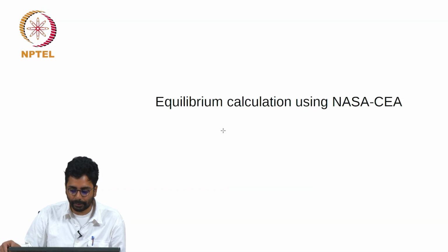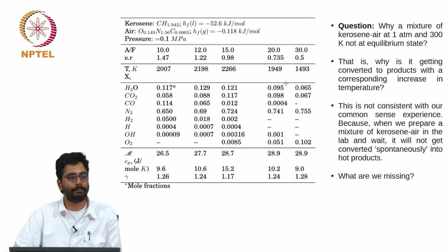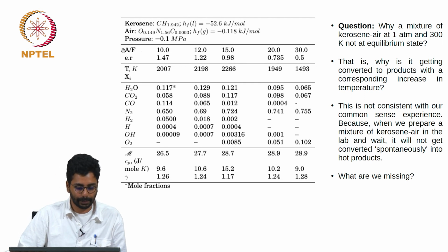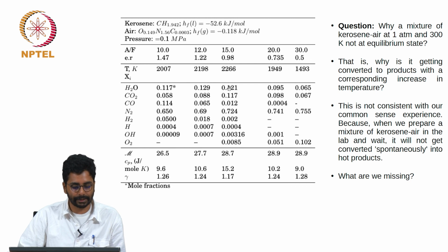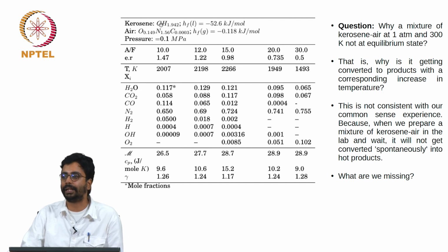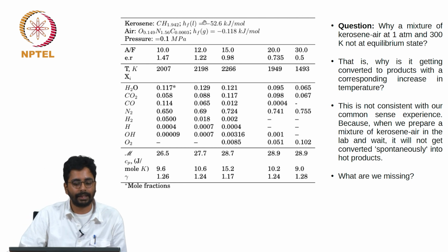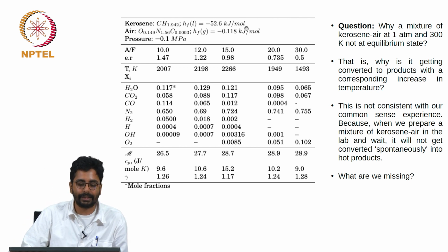Anyway, we will have a demonstration later, but I will just give you one example case of results. What is presented in this slide is equilibrium composition for kerosene air mixtures. Kerosene is taken to be, for example, this is one case where you can use the enthalpy of combustion to back calculate the formation enthalpy.